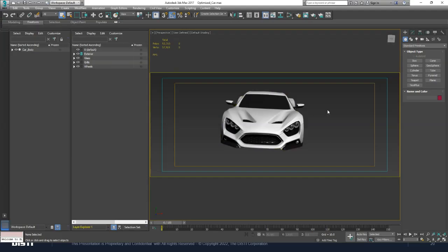All right, the same color that we were looking at, we have that open here in 3ds Max. If we drop down our hierarchy in here, you can see that we have our main body that has a glass, a door, grill, wheels, another door in there. One thing to mention on the hierarchy is if you are going to have animations applied to them, make sure your hierarchy ordering is correct. Because when they come into GeoStudio, those animations are going to play from the child or the sub object up to its parent. So do make note of your hierarchy ordering, especially when you're doing animations.